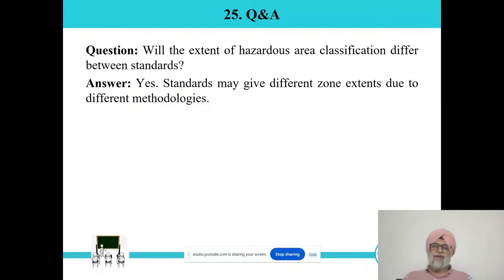So, in case of Indian standard or NFPA, there are some general examples. In case no example is available, you have to select the closest one. So ranges vary. In that case, with IS and NFPA, the hazardous radius will be more, while if you calculate as per the IEC guidelines, you will find a lesser one, so more specific.